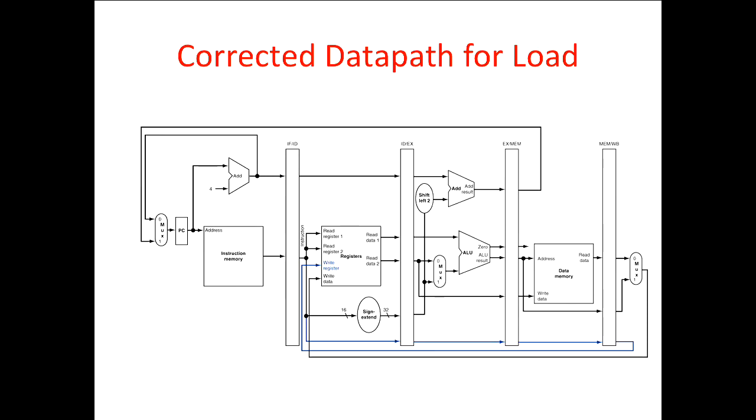As you go down the pipeline, you use the local version of the instruction register to decode and control things, so you have the right instruction going along with the right data. Just keep them paired all the way down the pipeline. So this needs more registers, more circuitry, more stuff to hold on to those bits and shift them down the pipeline along with the data. That's what's being shown here, this purple line here.